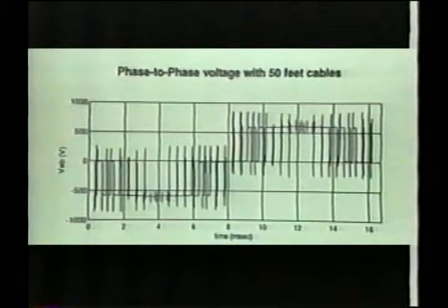If we have a look at the pulses that are generated by pulse width modulated drivers, we'll have one fundamental waveform that's typically of 60 Hz or less, and the fundamental waveform will be reproduced by a series of fast pulses, each of which will have a duration of tens of microseconds, and at the beginning and the end of each of the pulses, you'll get some oscillation lasting from 5 to 10 microseconds.